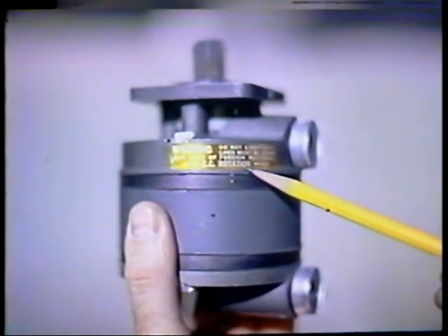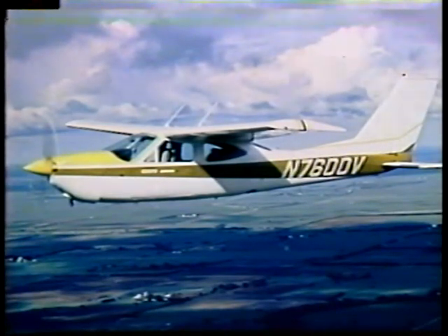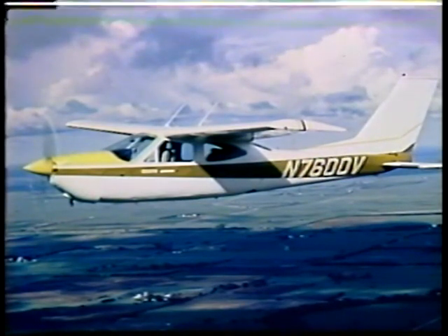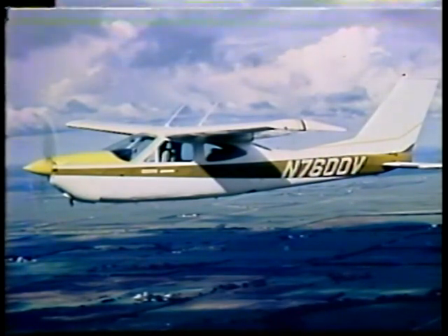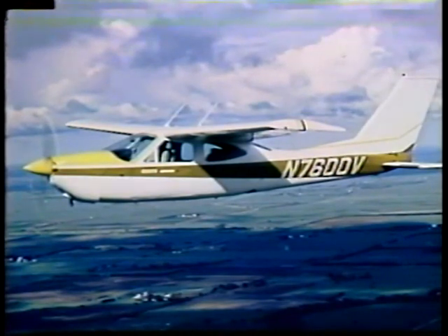To maintenance personnel installing unidirectional pumps, it is extremely important to match the rotational direction of the pump with that of the engine drive pad. The direction of pump rotation is determined by simply looking at rotation of the drive pad, or by viewing the pump from the anti-drive end. With this new generation of dry air pumps, aircraft owners are often able to obtain a pump service life comparable to the total life of the engine. Maintenance costs are less, and greater reliability and air safety are also achieved.